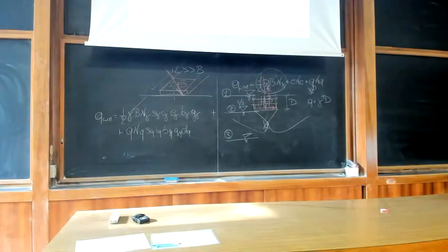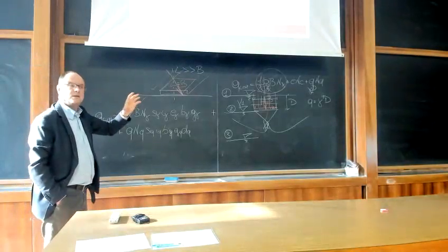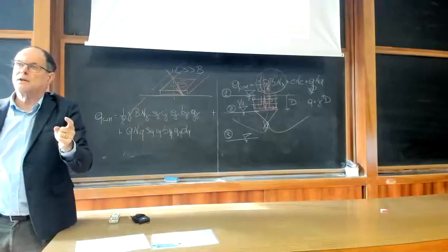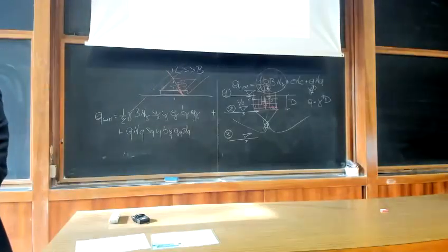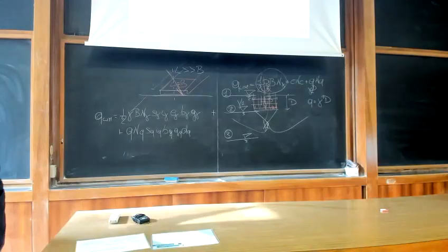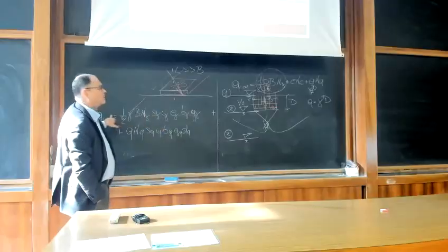So irrespective of the specific expression, these authors do not agree even in the direction they should go, increasing the limit pressure or reducing it. This is a bit misleading. The depth factors are typically not used, but they are always greater than 1. The load inclination factors can reduce significantly the limit load.